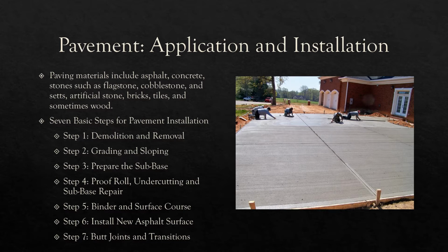Step 2, grading and sloping. It is important to ensure that water will run off appropriately. Proper water drainage is vital for your asphalt because water is a major cause of damage, including potholes, cracks, and heaving. Step 3, prepare the subbase.